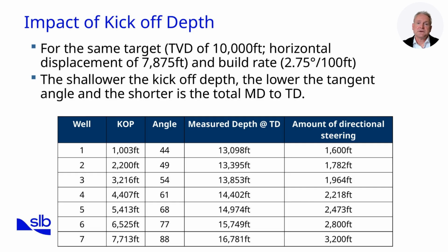Ultimately, kick-off depth should be selected not just on paper, but through integration of rig capability, BHA design, hole cleaning hydraulics, and reservoir entry requirements. The optimal solution balances measured depth, inclination, and operational risk to deliver a trajectory that is both drillable and productive.